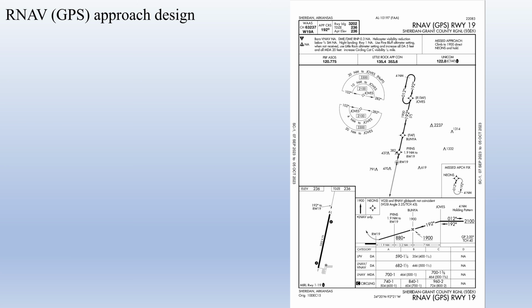Another common approach design is to omit the two outboard initial approach fixes and just have the intermediate fix pull double duty as an initial approach fix with a holding pattern in lieu of a procedure turn and an intermediate fix. With this design, aircraft approaching from the upwind side of the intermediate fix can still navigate to this fix and in on the approach, but anyone approaching from the downwind side of the fix will be stuck doing a turn in that holding pattern procedure turn to get established on the approach. This type of approach is more common at smaller airports and approaches to shorter runways.